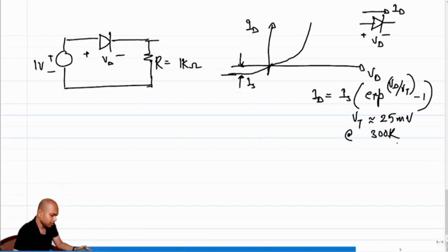So we need to figure out the currents and the voltages across and through this diode or in this network. So essentially what we are saying is, if I know this, how do I figure out this current I? And for that you will have to resort to some graphical method, right? And you can write down the equations. How will you go about writing it? So we know that the Id Vd characteristic is this. So essentially I is common.